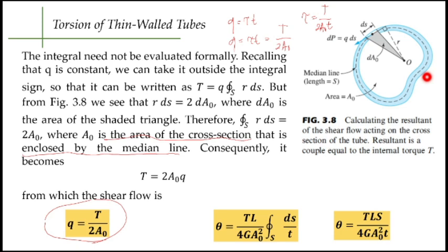Now also, since we are now able to solve for the shear stress in terms of the force that caused the material to have shear stress, which is the twisting force or the torque, next we ought to derive the relationship between the amount of displacement, which is the angle of twist caused by the twisting force or the torque, which is this one.